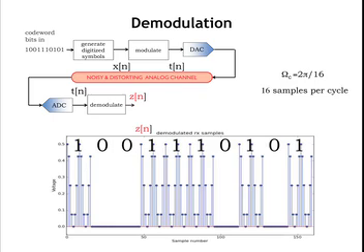So this was a 0-1 waveform that we transmitted, but we're demodulating it using a scheme that could have actually handled a signal that went negative as well. But this example doesn't have a signal that goes negative. It was the one that I showed you earlier, but you can see that the average value here is picking out exactly what you want. So your challenge now is to get rid of the double frequency piece.